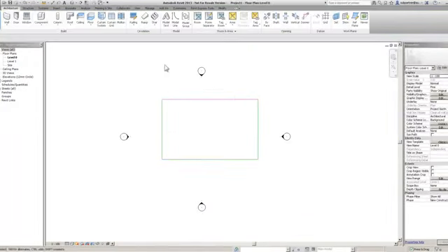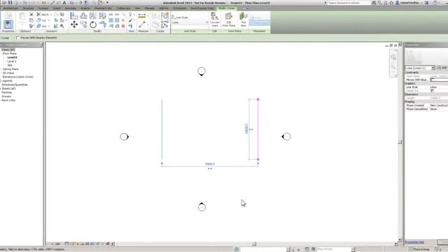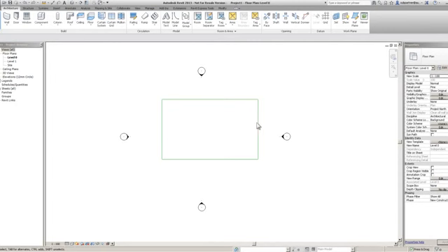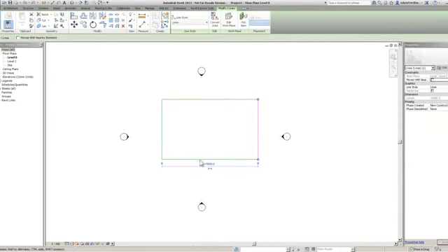If I just delete those 2 lines like that and still pick that line, it will still give me the setting out of that. In this case it has given me the length of it as well, but that's by the by for what I'm trying to show you. I'm just going to hit undo to bring those back. So basically now, by selecting that line, you can still pick the temporary dimension, and we'll just change that temporary dimension to a new distance. The object that we have selected will now move to accommodate the new input.